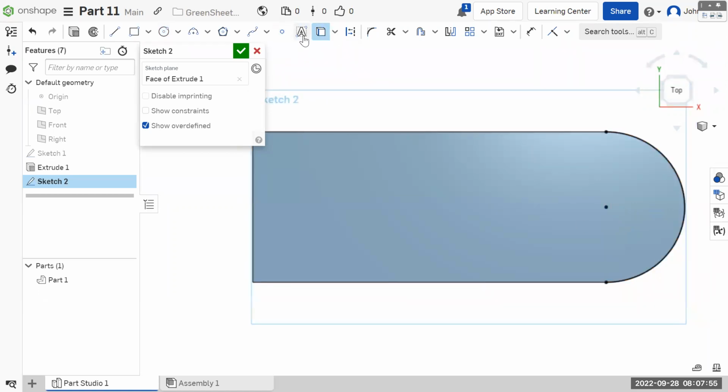Yeah. All right. So if you click on use, which is this tool right here, and then click on the edge of use, and then click on the arc of the part right here, it will project that point so that you can see what you want to snap onto. So we need a circle that's centered here and dimension that to 2 because it's the diameter. And we need another circle over here, and I'm not sure. So it'd be nice if we got some sort of soft snap that let us know that we were lined up. Oh, well, there you go.